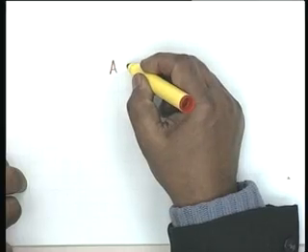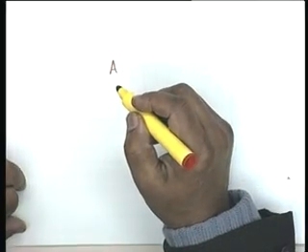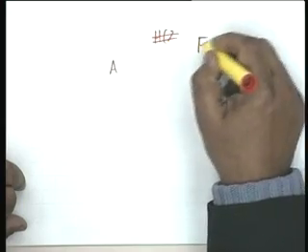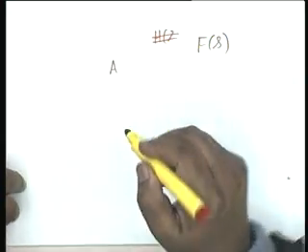We shall consider sinusoidal network functions. That is, what we have considered here is f of S, a function of the complex variable S. How does this function behave on the j omega axis? Now what does the j omega axis correspond to? It corresponds to sinusoidal excitation. As you know, e to the j omega t is cosine plus j sine omega t, so its real part as well as imaginary part is sinusoidal.